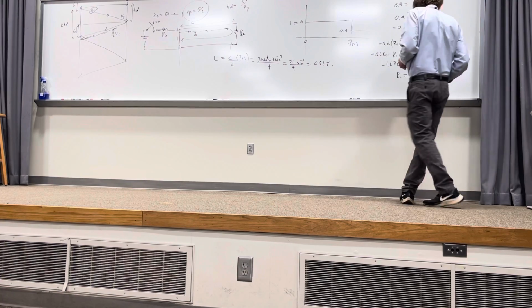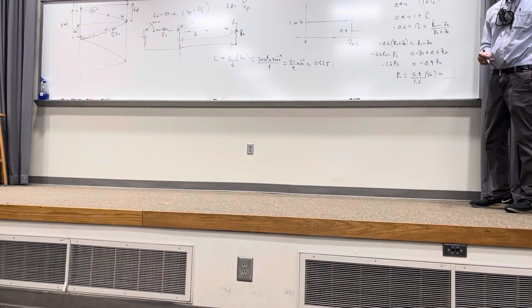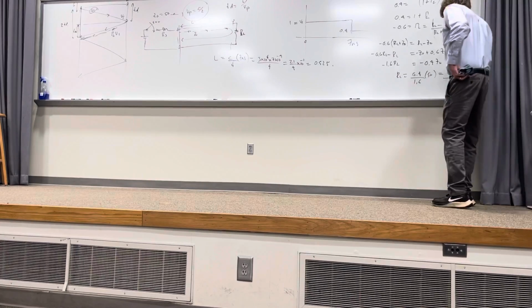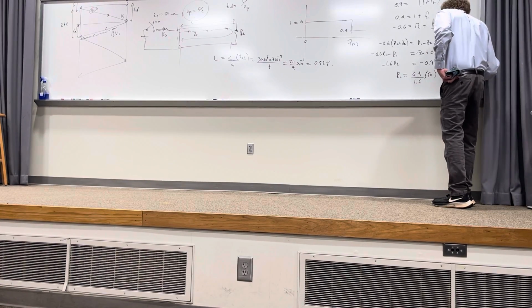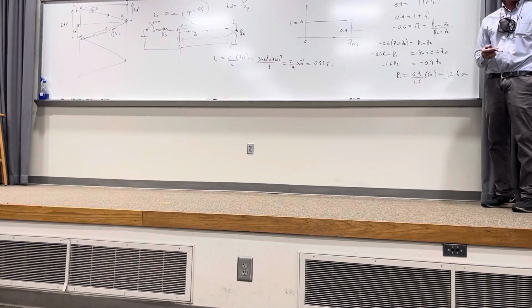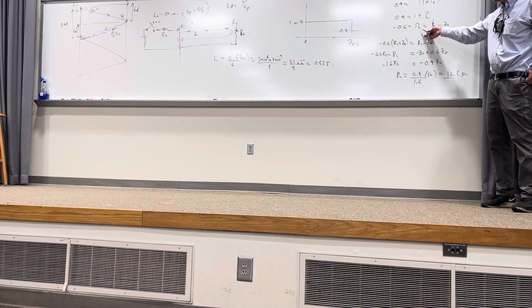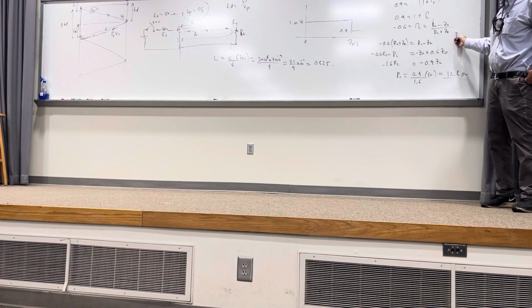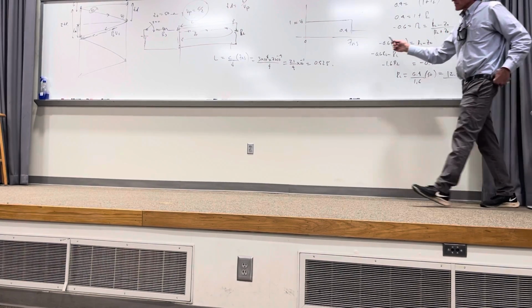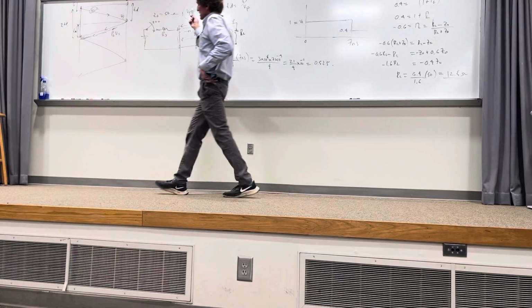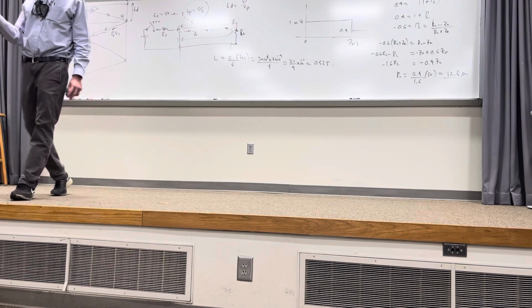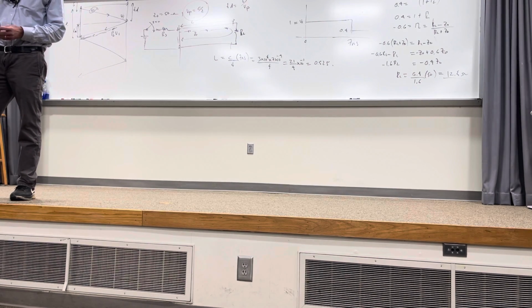Z0 is 50, and what is that equal to? 12.5, is that the answer? Let me make just one comment to be clear about this. The real thing is knowing that gamma L is equal to RL minus Z0 over RL plus Z0, and that the reflected pulse when it comes back is added to VS to give us the 0.4. That's the only trick in the book for this problem.